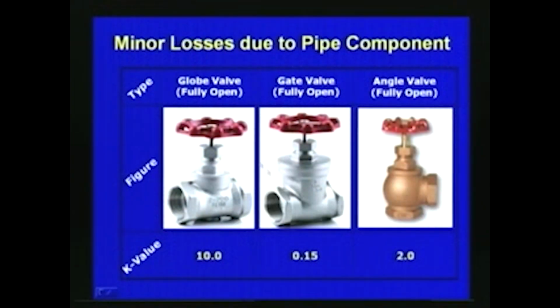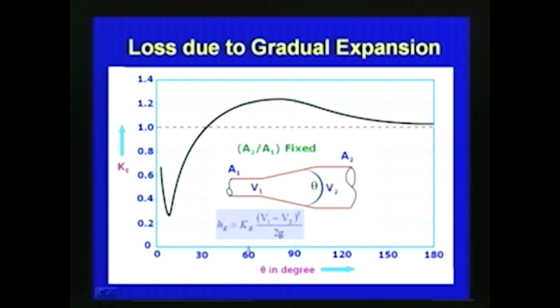For these also, since they are controlling the flow in some way, there will definitely be a pipe loss effect. So here in this slide, depending upon the type of the valve or type of the gate, the loss coefficient K will vary. The type of the gate or valve is put here with the corresponding K value. As we discussed, the pipe loss is put in terms of K v square by 2g.